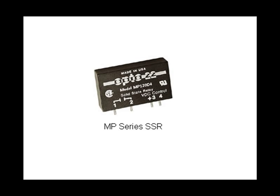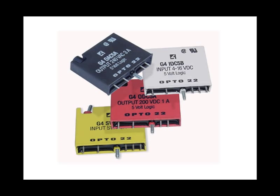Here is an example of several variations of solid-state relays. The black module is controlled with 5 volts DC logic and will switch up to 3 amps at 240 volts AC. The white module converts a DC input signal in the 4 to 16 volts DC range to the 5 volt DC level used by the controller board. The red module is controlled by 5 volts DC output from the controller and will switch field devices requiring 200 volts DC or less at a maximum of 1 amp.